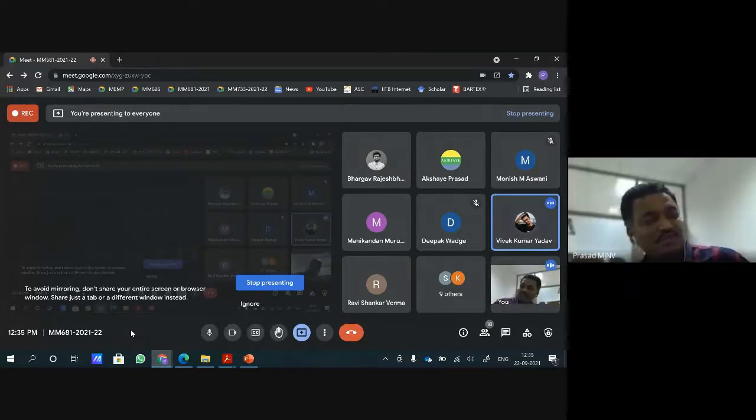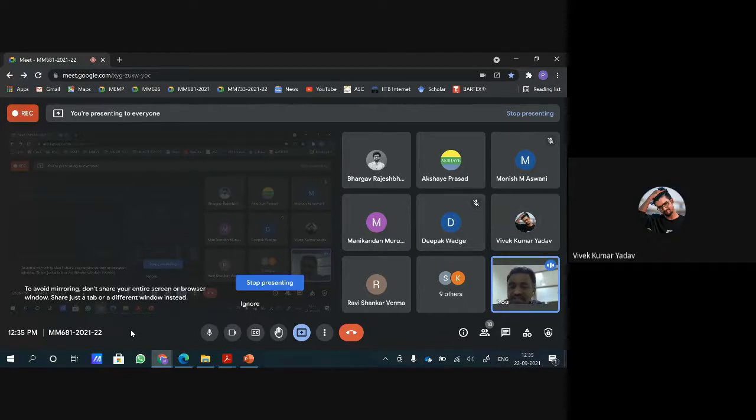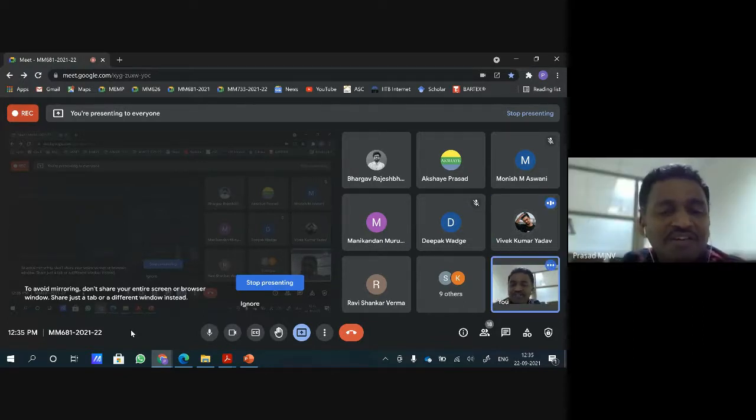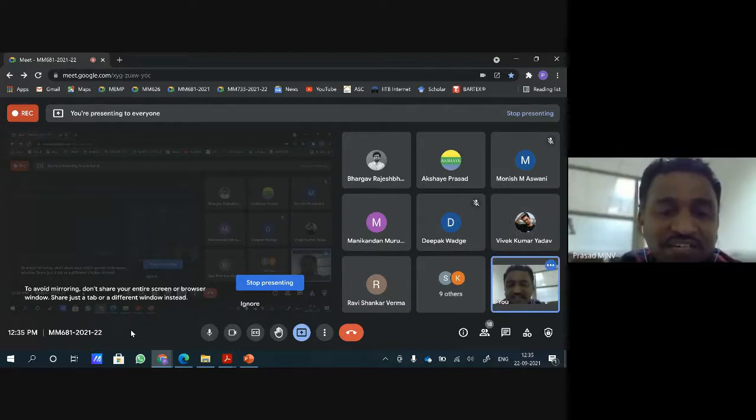No, no. See, usually deposition techniques will give you some stresses. Some stresses are going to build up, though it's a pure metal. Your sigma naught is more. What does that mean? It's not only a pure crystal effect. Apart from the pure crystal grain effect, we also have other factors like residual stresses, which are additional stresses. We are talking about depositions, so a lot of stress is going to develop. In annealing, we are removing all the stresses.